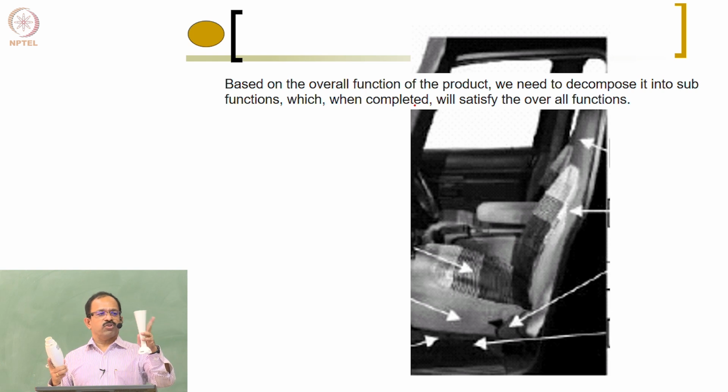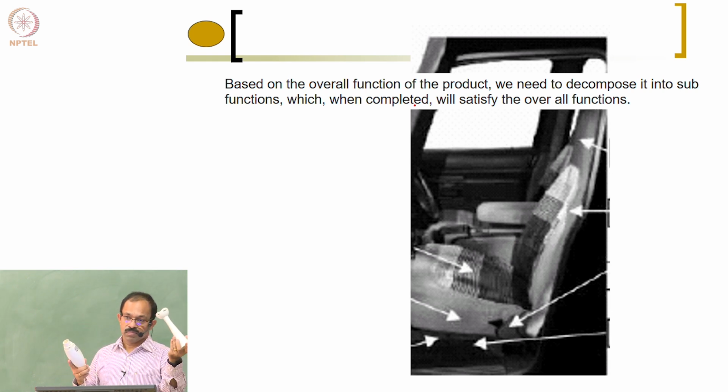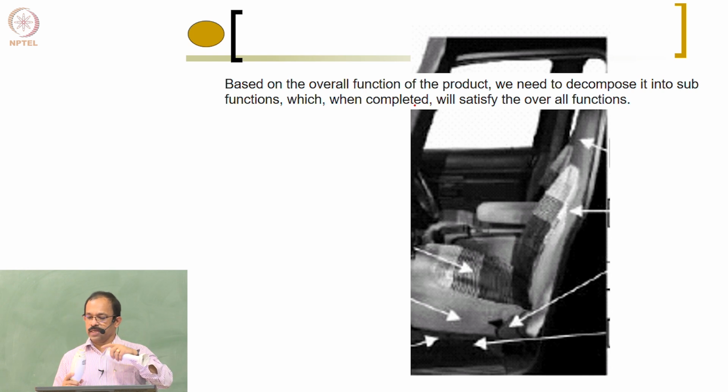So, what is the function of this particular part? Is there any particular function for this? Yeah. So, basically, you have a rotation here. That rotation needs to be transmitted to the blade, right? That transmission is done through this. But then you could have connected the blade here itself, right? Why not connect the blade here itself? Because we need an access point, a holding point, and a distance from here to here so that you can put it into a jar, right?